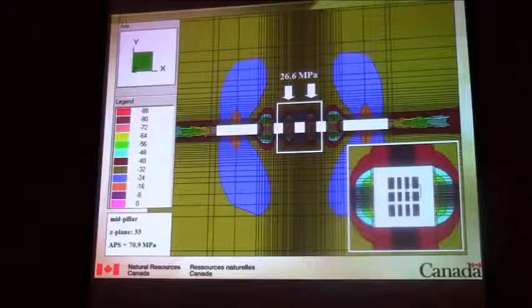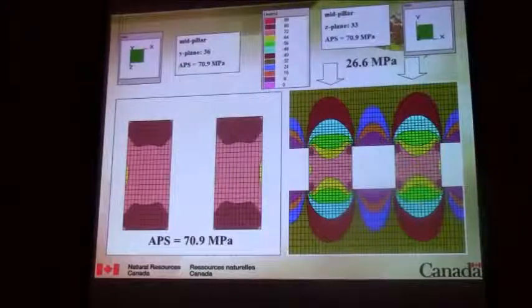When you're working in mine seismology and rock engineering, you're not just working with a rock in one state. It's not always elastic. As you excavate, the properties change as it starts crushing and losing its strength. In different parts of your model, different things are happening. It's like the rock is undergoing a change of state, like working with water, where sometimes it's a liquid, sometimes a gas, and sometimes a solid. So you have to have numerical models that can cope with these changes in what we call our constitutive equations.